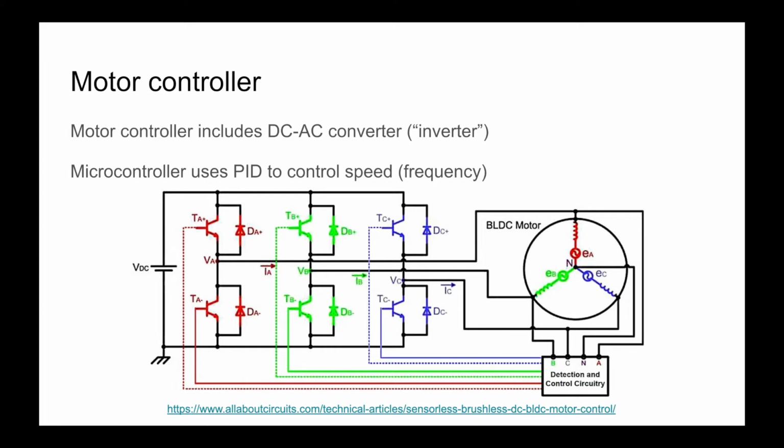As we can see from this, a brushless DC motor isn't actually DC. It just takes a DC input and then converts it back to AC. This shouldn't be all that surprising, as the motor requires a continuously oscillating input in order to provide the rotational output. As one can probably guess, the output of the inverter is never a true sine wave, but rather a high-frequency combination of DC steps that emulate the operation of an AC signal.